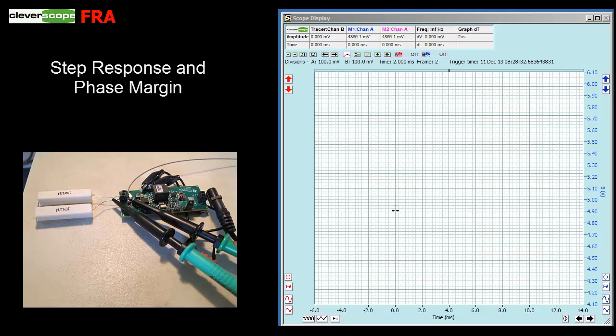Here we go. I've got a mechanical switch which applies a 2.5 amp load at 5 volts. You can see that this caused a transient in the output voltage. The output voltage has recovered very quickly, but you can see also that there is much more switching activity after the load was applied. The power supply looks stable. I was using a mechanical switch, so this is probably switch bounce in the mechanical switch.